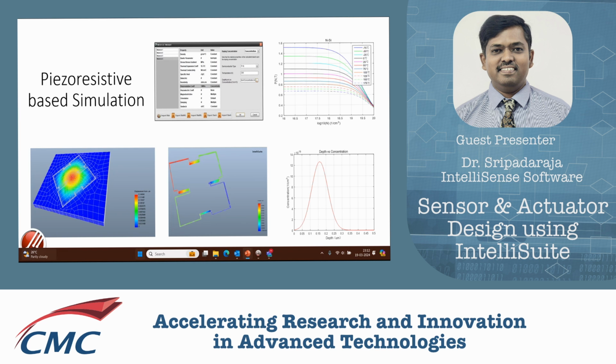Define the process recipe, define the piezo-resistive parameters based on the process that you have adopted. You are doping a p-type in an n-type semiconductor or an n-type in a p-type semiconductor. Based on that, at what temperature and what is the depth of the implant, the piezo-resistive coefficients, pi11, pi44, get decided.